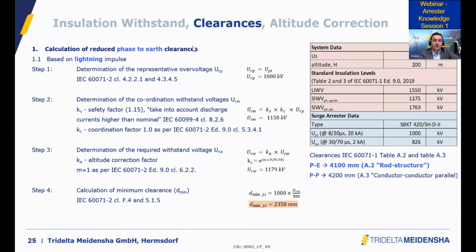That's why it's very important to look at the data sheet of the surge arrestor and to look at the different residual voltage for the currents that you need. Normally, we use the nominal discharge current. You can use a higher current if you want to have a safety margin, but typically, this is correct. You are no longer looking at the maximum lightning over voltages, for example. You are looking at the protection level of the arrestor. And it's good that you mentioned protection area.